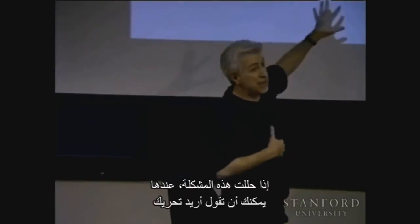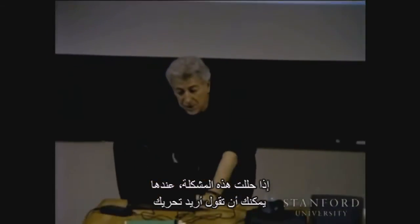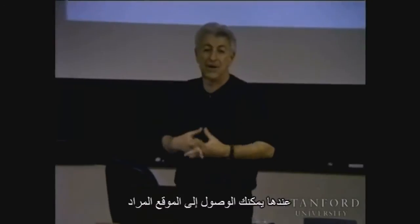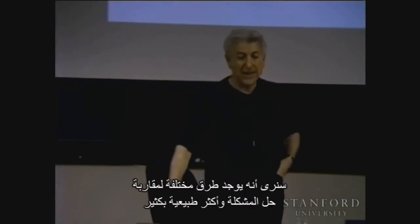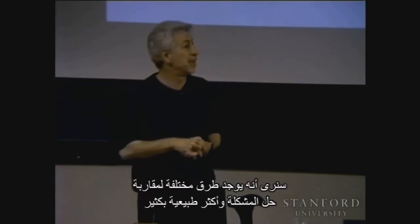But if you solve it, then you will be able to say, I would like to move each of those joints from this current joint position to this joint position. So you can control the robot by controlling its joint positions and by creating trajectories for the joints to move, and then you will be able to reach that goal position. Well, this is not the most natural way of controlling robots, and we will see that there are different ways of approaching the problem that are much more natural.